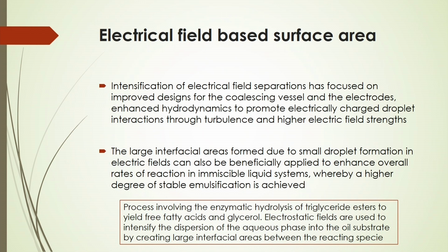In this case, intensification of electrical field separations has focused on improved design of the coalescing vessel and the electrodes that enhance hydrodynamics to promote electrically charged droplet interactions through turbulence and higher electric field strengths.